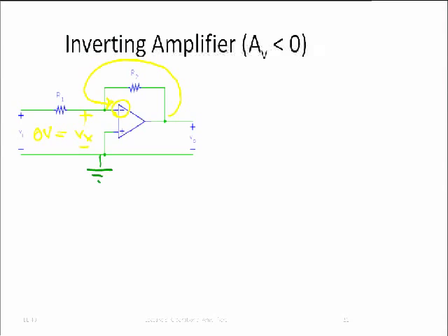This voltage here is 0. Then what's the voltage here at the minus terminal of the op-amp? This voltage has to be 0, right? Okay. So why is it 0? Well, we figured it out using some math. Now we just know it, right? Don't worry about it anymore. We've checked it's negative feedback. Consequently, it's going to be 0. Okay?